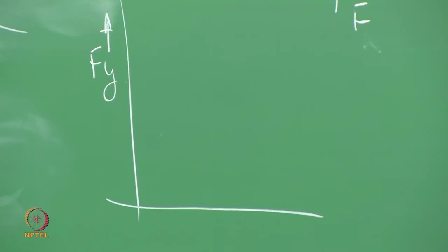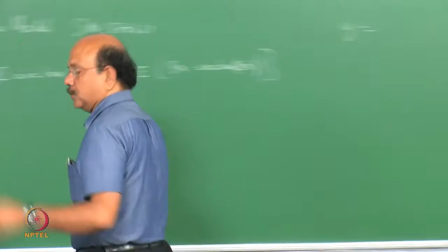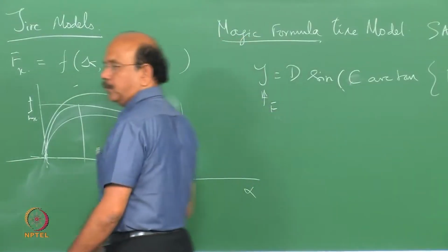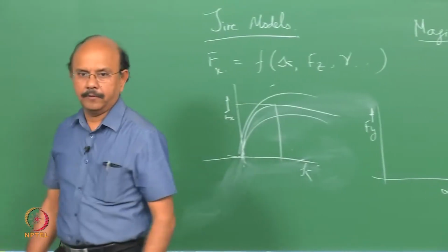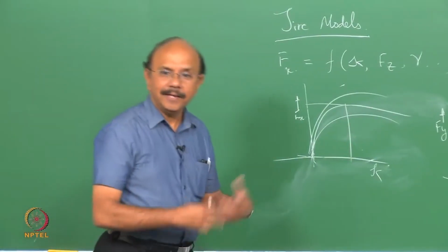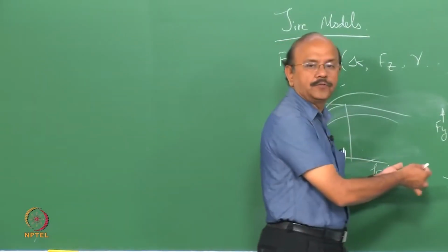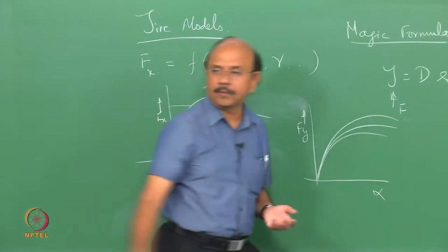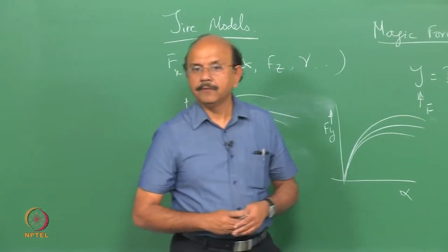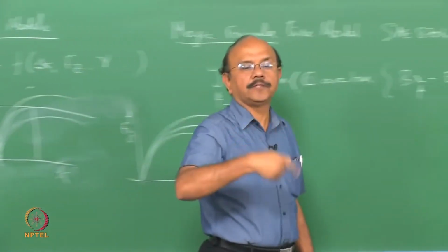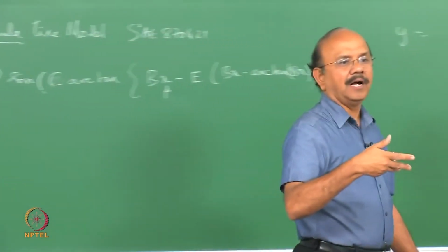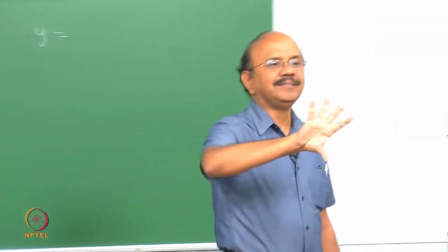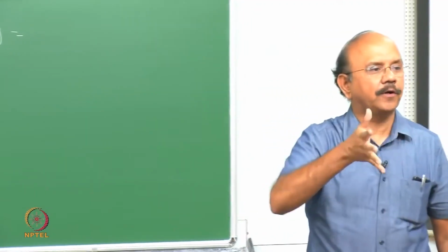Here again there is going to be a load transfer due to the roll, and again there is going to be a change of these forces with respect to Fy and so on. So when I do a calculation, I have to take into account this kind of transfer of loads.